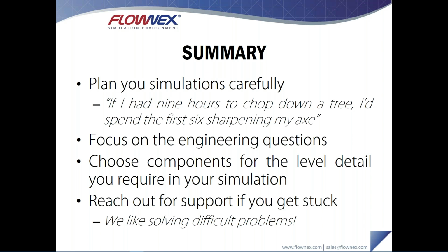So if you're modeling a basic power cycle just to analyze the efficiency with changes in the cycle design, don't go ahead and specify complex compressors using compressor charts. It's going to waste a lot of time. Modeling the compressors in a simpler fashion would save you a lot of time and get you similar results. So choose the level of detail in your components carefully. Don't just always resort to the component whose name seems to match as best as possible.